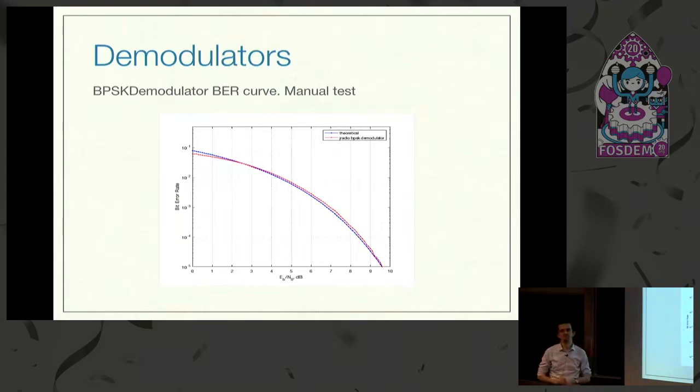That's wrong for low SNRs. There are about 1 million papers out there that use the MATLAB BER curve, and they're all wrong, because for low SNRs the curve is wrong. Yeah. But this BER curve covers the AWGN channel. If I want to test against a multipath propagation channel, then the BER curve will be different, and it might be worse than the theoretical. Even for the high SNRs you're only like... Yeah, it looks good. I spent some time on tuning it, and actually I took a lot of code from GEO satellites to do it.